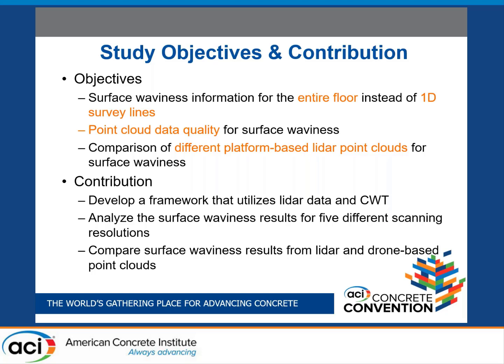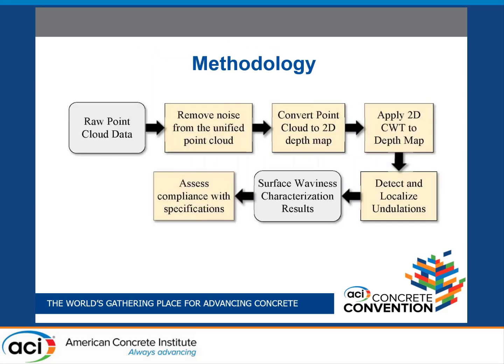If you can obtain the same results with lower quality data, that is better, because it's computationally easier to process. We also wanted to compare tripod-based, also called terrestrial, laser scanners versus drone-based point clouds to characterize the surface waviness.